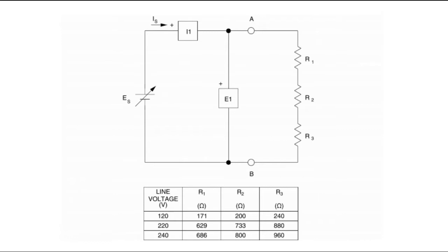Set up the series circuit as shown in this figure. Connect your DAI at circuit points A and B and use DAI I1 to measure the circuit current. Ensure that the correct polarities for voltage and current measurement are respected when connecting the DAI, and that the DAI low power input is connected to the main power supply. Next, display the metering application and select setup configuration file ES11-2.DAI. Note that the metering setup configuration can be changed during the exercise if desired.